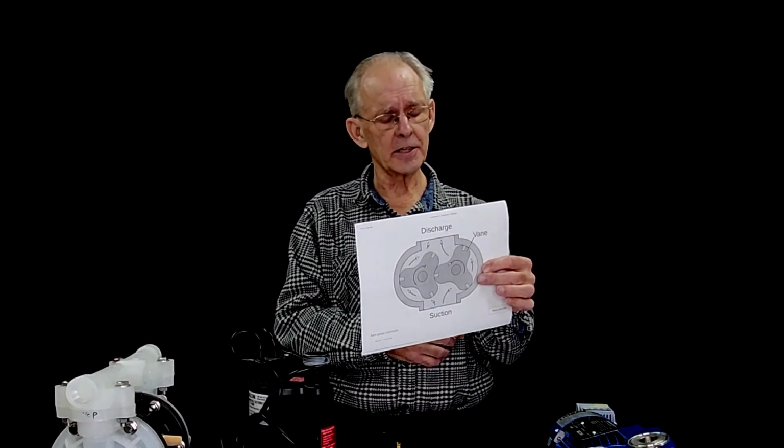Then we have a lobe pump. A lobe pump has two rotors with a seal at the ends. These white areas are a seal to help reduce the leakage between the rotor and the housing. And these are positive displacement and reversible. And the flow, as you can see, goes around the outside, not through the middle, which you kind of would think it would. It actually flows around the outside. So lobe pumps are used for pumping sewage and things that are thick, high viscosity and so forth.